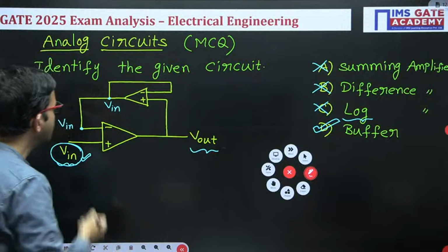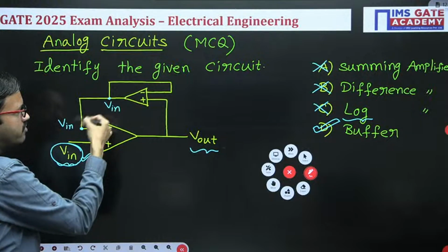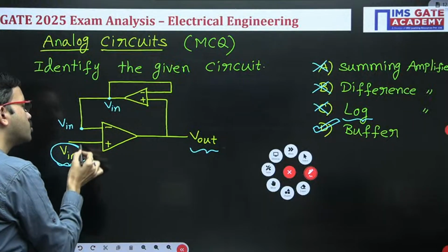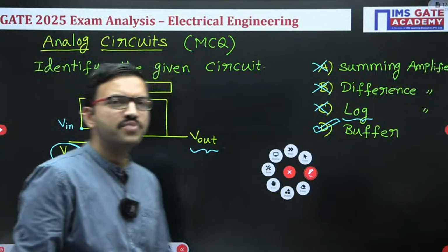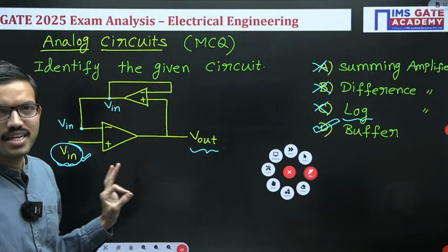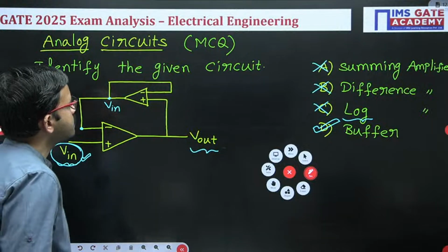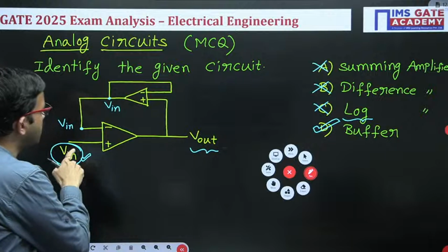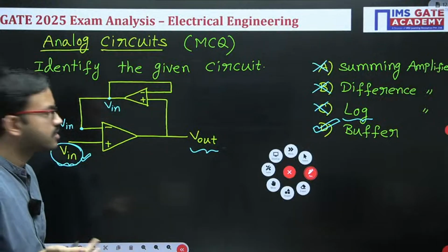That means it is very simple. It is as if you shorted these two with a wire. Exactly here short is happening, but not physically with the help of wire; rather it is happening virtually. That's why we call it virtual short. Suppose if this voltage is ground, 0 volt, then we call it virtual ground, like that.